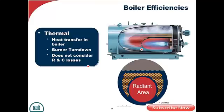And of course that energy is going to vary as I turn the burner down. And I can have a 4-to-1 turn down, I could have a 10-to-1 turn down, I could have a 20-to-1 turn down burner. It's all about the amount of energy going into that unit that is being absorbed by that heat exchanger, so it goes into the water to make hot water or steam.